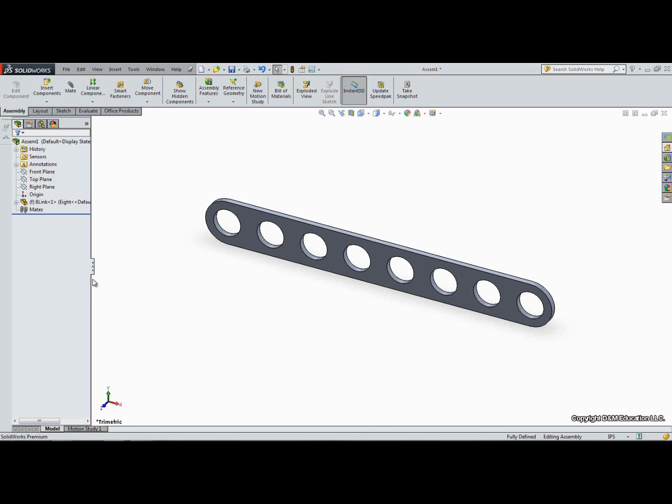In an assembly, fix the first component to the origin or fully define it to the 3 default planes. Unlike in a sketch, it is okay to have components, however not the first one, that are underdefined, as this means that there are components in the assembly that can move.